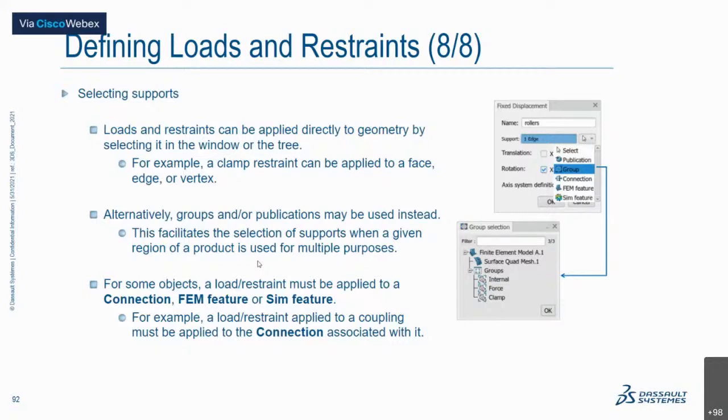In this case, it is very efficient because if you make any change during the assignment, you don't have to click on all of these components individually and apply it. You can just select your group, group one, and change the value there, and it will be automatically updated for all four of them. So this is one very helpful way for a complex geometry. Maybe you could use this.